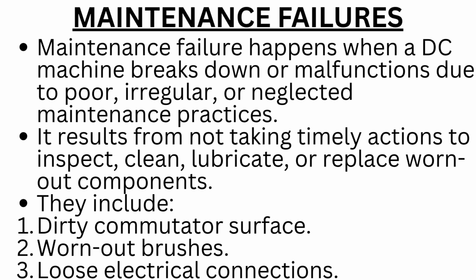Maintenance failure happens when a DC machine breaks down or malfunctions due to poor, irregular, or neglected maintenance practices. It results from not taking timely actions to inspect, clean, lubricate, or replace worn-out components. They include dirty commutator surface, worn-out brushes, loose electrical connections.